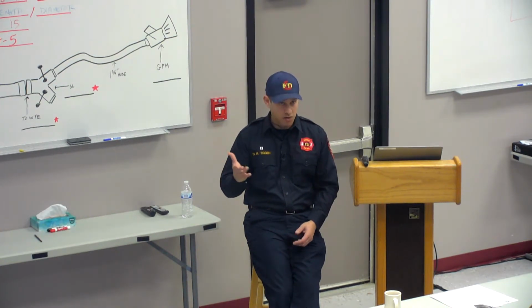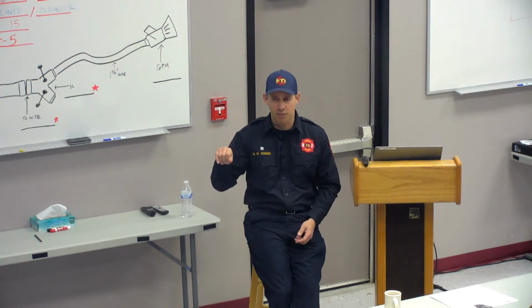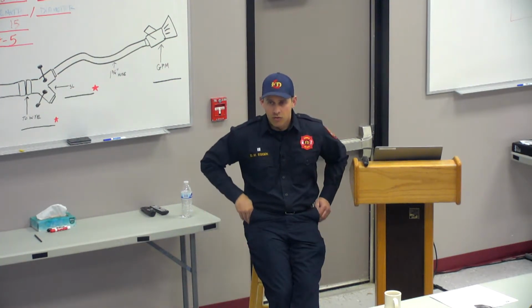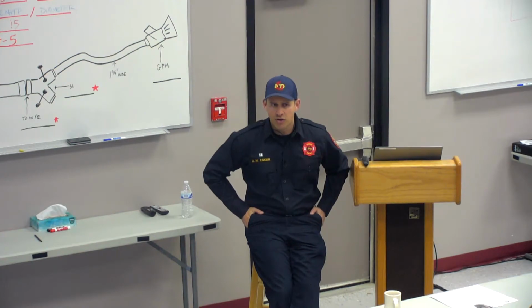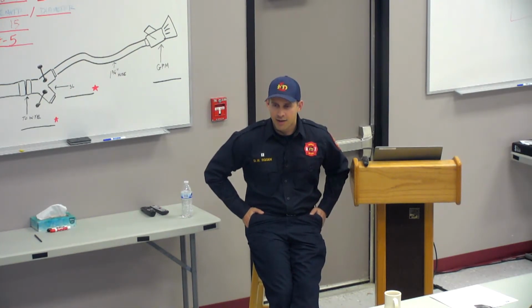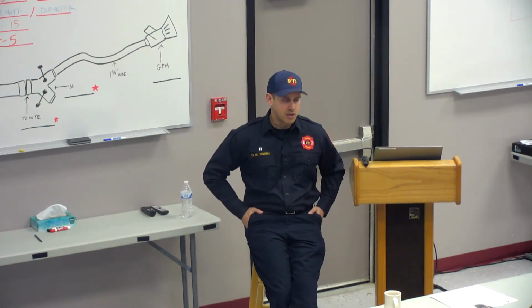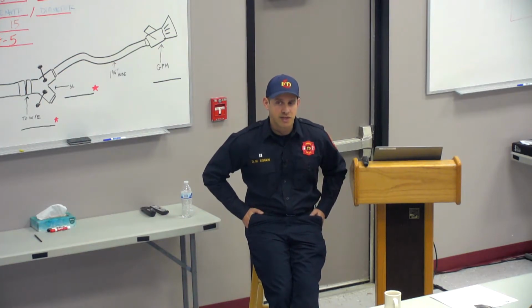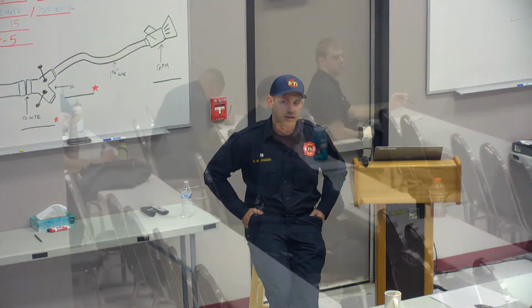We just made mention of when we're thinking about turning that pressure relief valve off. When do we go from pressure to volume, since we're talking about transfer valves as well? Half the capacity of your pump. Vince, not to keep picking on you, but since you're answering, about 750. What is your pump capacity at Engine 6? 1500. So about 750, you're going. So that 1500, what does that mean? Your pump capacity is 1500 at, anybody?